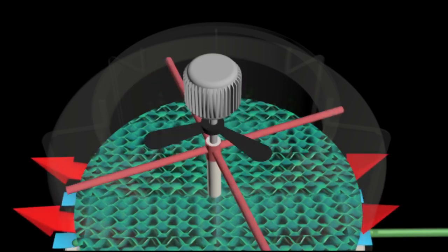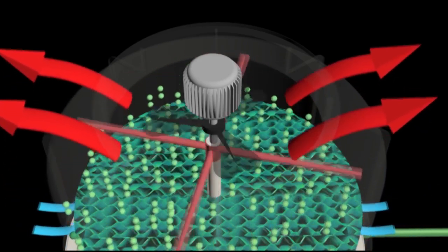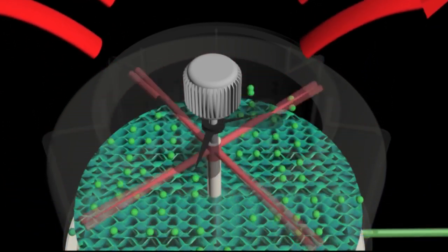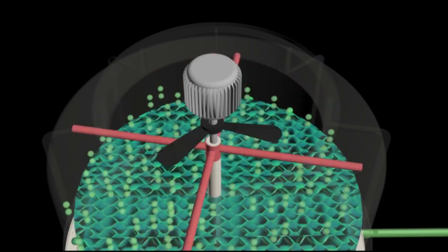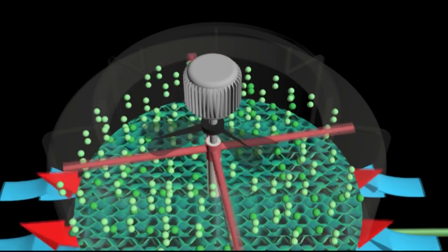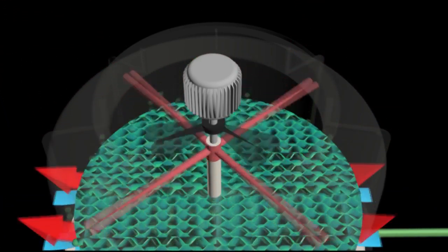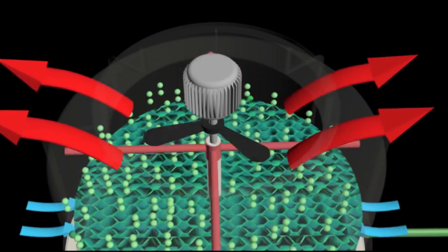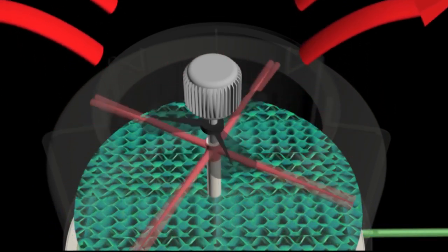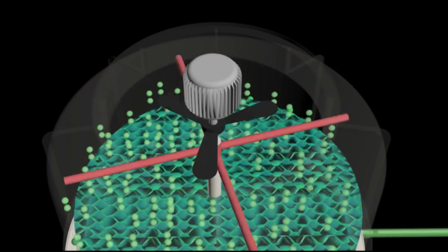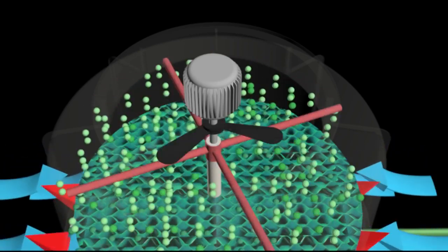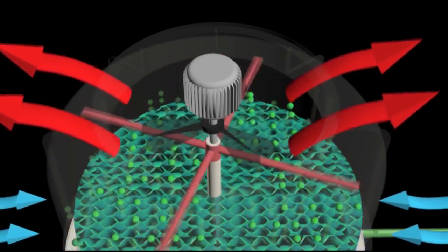This can delay the time so the heat can be absorbed more effectively by the surrounding air that passes through the fins. Air through the fins is forced by a rotating fan on the sprinkler blade rotated by the motor. This fan rotates with its gusts upward. This will cause the air to move from the bottom to the top of the cooling tower, which is opposite to the flow of the condenser water.